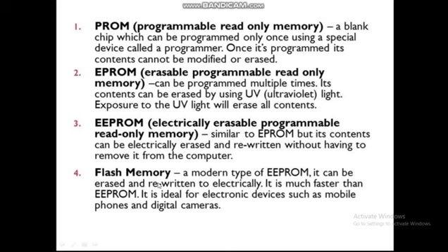The flash memory can be erased or reprogrammed on the system board itself, and it possesses the feature of quick pulse programming. That is why the name flash memory has been given, due to its fast reprogramming capability, and it is used for storing codes. Conventional E-square PROMs are used for storing parameters only.